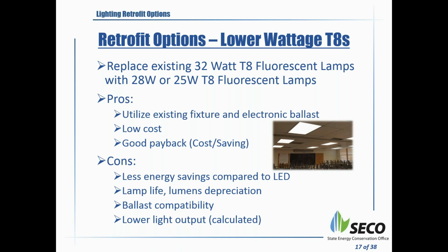And by the way, ballast compatibility has still been a problem if you've got an older generation of electronic ballast, or first generation electronic ballast. 28 watts would normally work, but the 25-watt lamps had some problems with that. So in that case, you had to change the ballast. And the only way you can know is that when you put the lamp in there and you see it flickering or something like that, then you know it's time to change the ballast too.